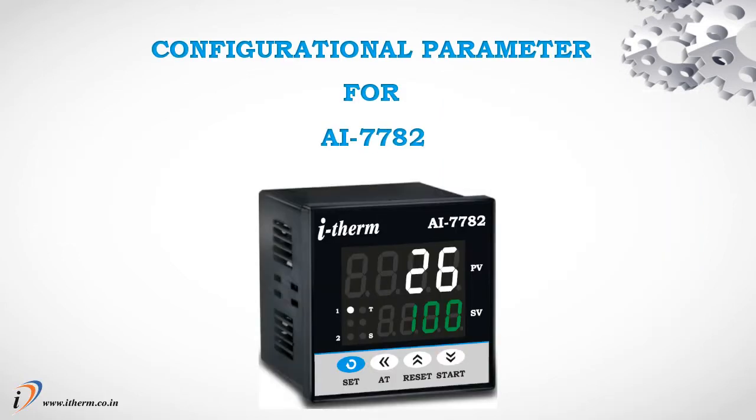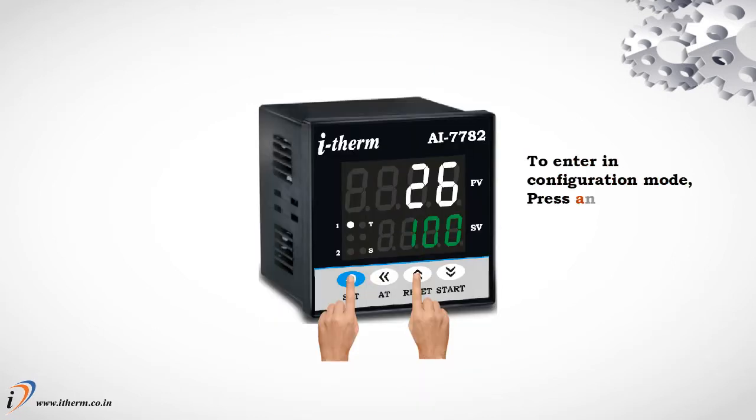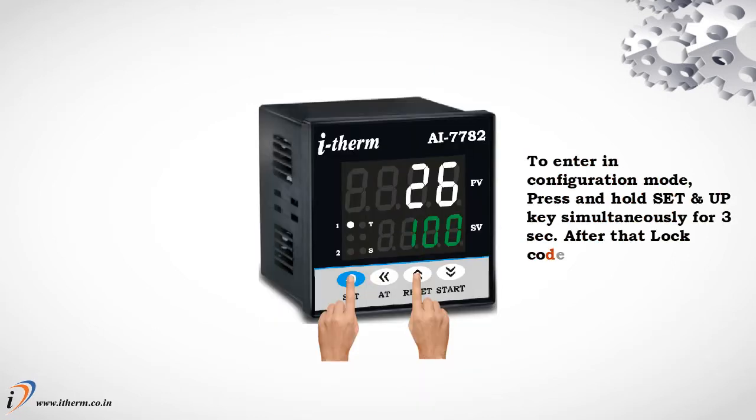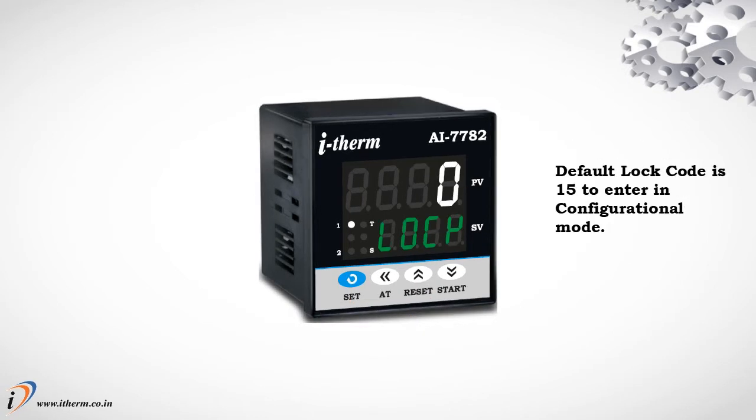Configurational parameters for AI7782. To enter configuration mode, press and hold the Set and Up keys simultaneously for 3 seconds. After that, the lock code will appear. The default lock code is 15 to enter configurational mode.